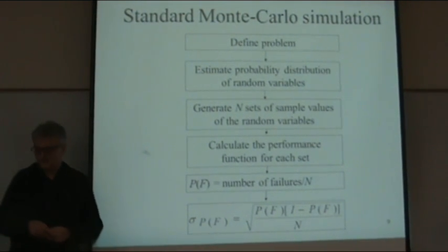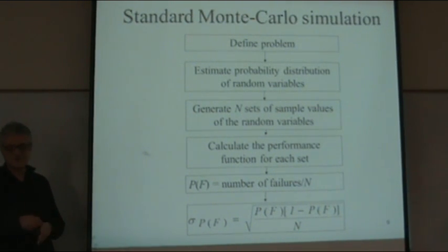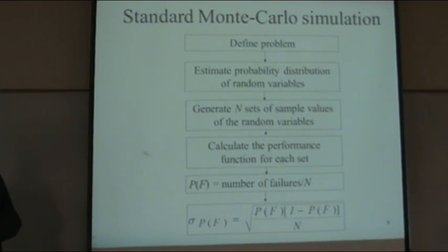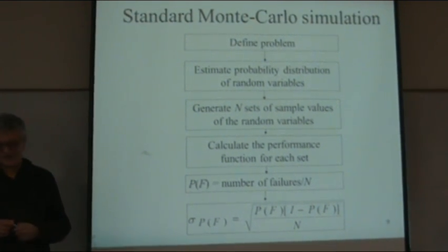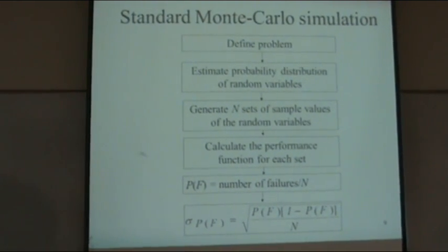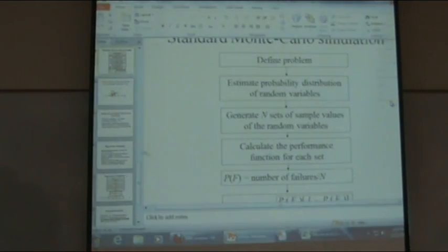You can perform Monte Carlo simulation, depending on the complexity of the problem, using different software. If you have a small problem, like just a couple of variables, like stress and strength, you can use Excel or MathCAD. Bigger problems, you may have to use a finite element program to do that. Okay, so let's see some examples using Excel.